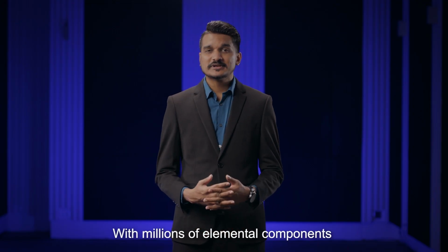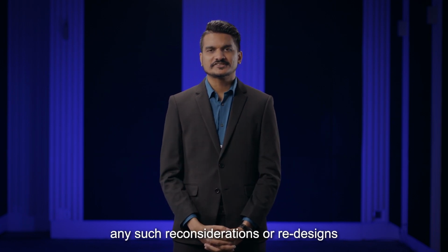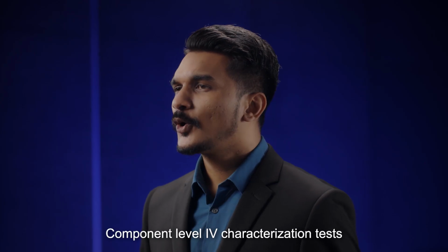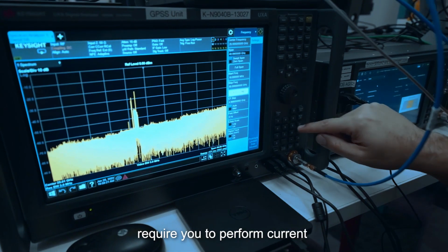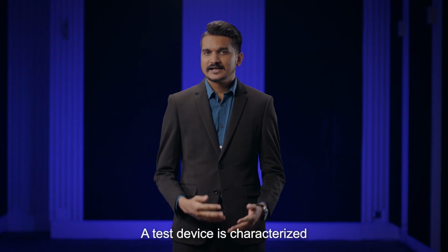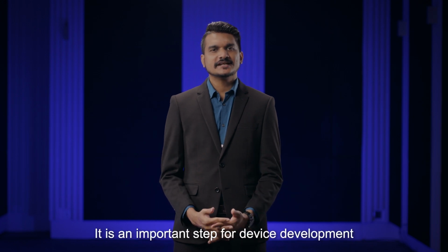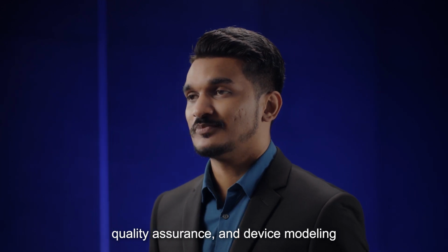With millions of elemental components such as transistors and diodes, any such reconsiderations or redesigns becomes a burdening task demanding thorough, reliable, and fast tests. Component-level IV characterization tests require you to perform current versus voltage measurements to help you understand your device's behavior. A test device is characterized through IV measurements, and key parameters are extracted from their IV curve. It is an important step for device development, quality assurance, and device modeling.